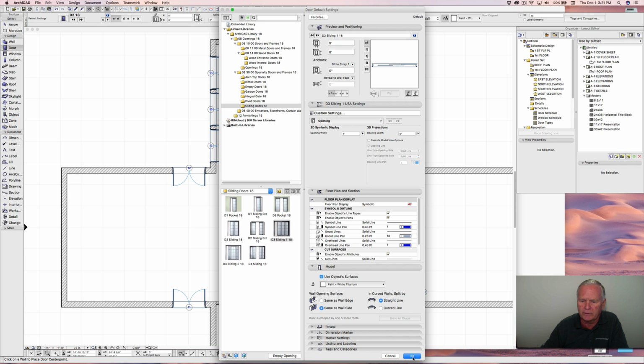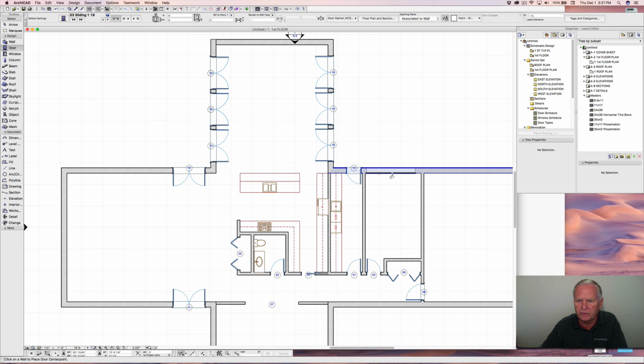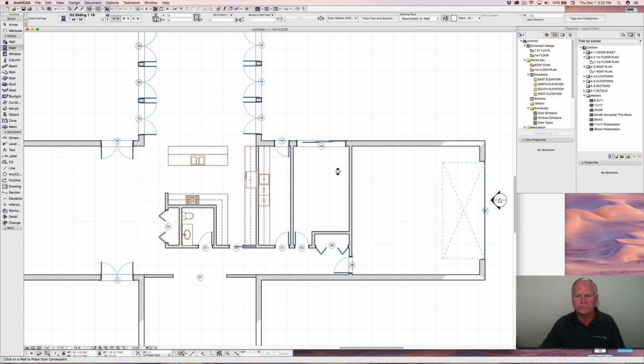And then we'll click OK, and we'd like to put it in center, and we're already in the center anchor point, so that's great. And we can click on either side here where that check mark is because it's measuring to the same point. We'll click on that as the outside, and now we want to look and see, do we want doors there, like so. And I normally would say that the sliding tracks would be on the interior, so as those doors opened, and I want it to open on this side, so I'm going to set it like this. Okay, so doors are in.